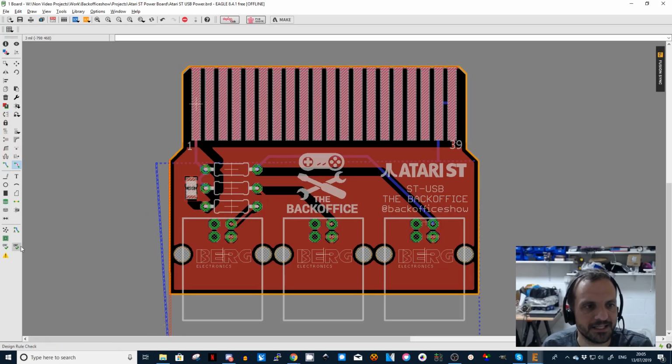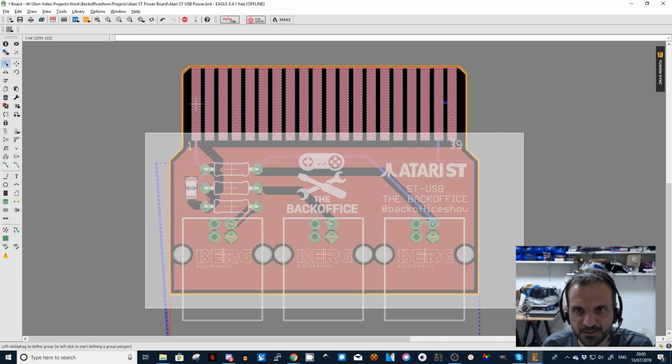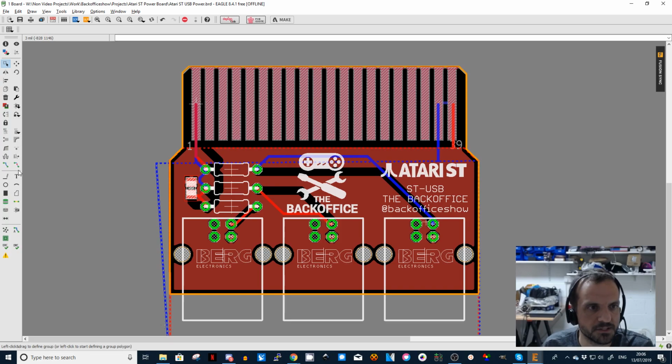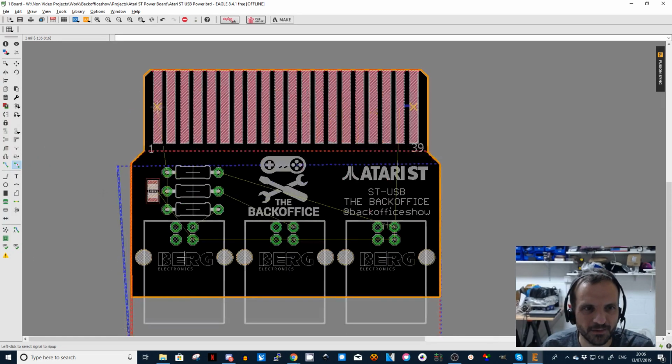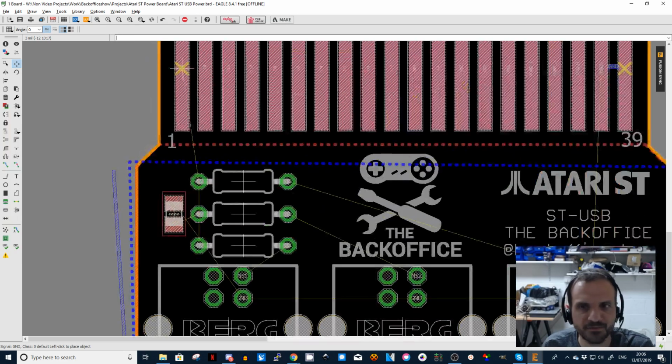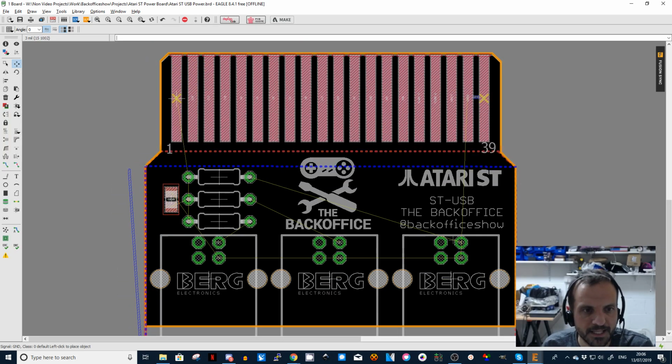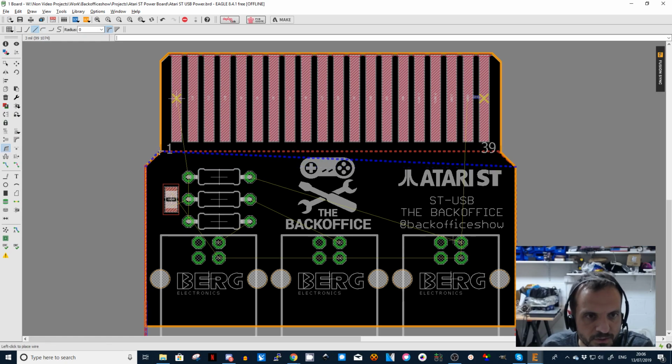Now, anyone watching what I've been up to, because I've been trying to put fatter tracks down by changing the classes for the net list, you'll notice there's actually a weird little bug in Eagle that I've just invoked where it's undone like 5 steps back. So be cautious. It does do that, and it does do that in the latest version as well.